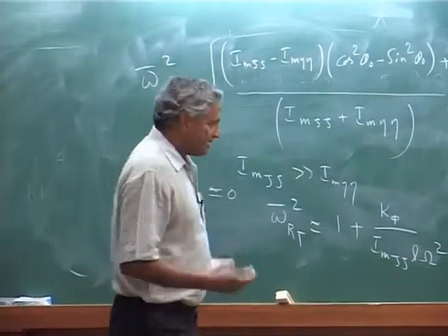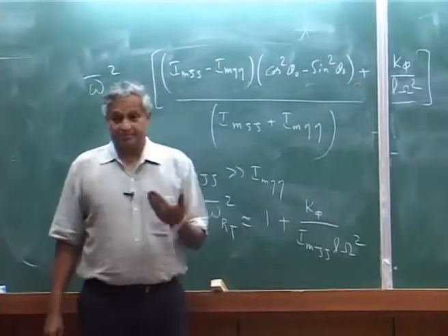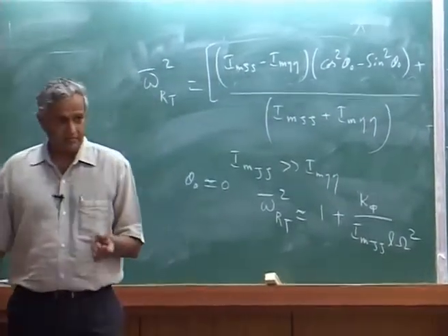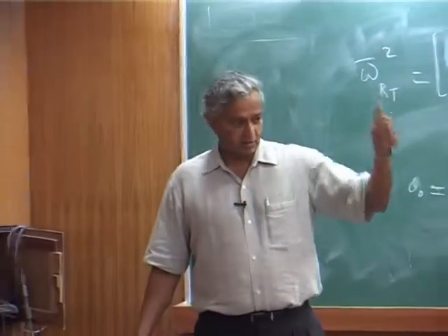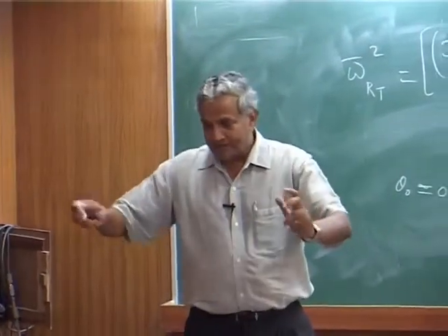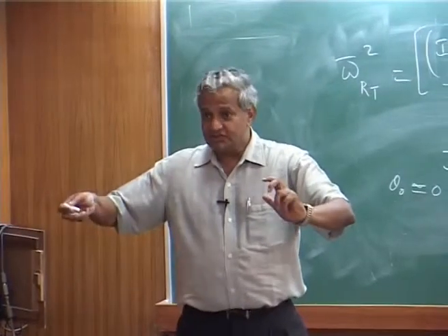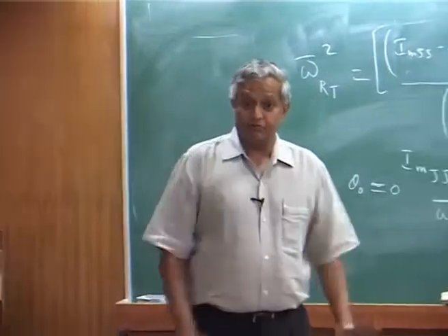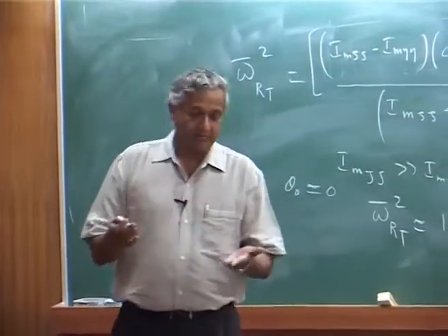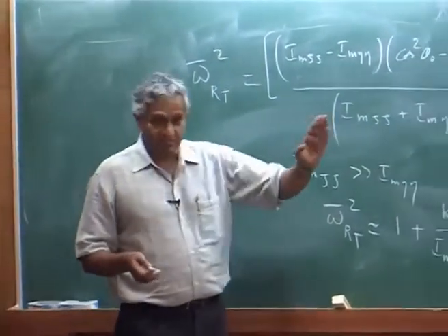So usually you try to design the control rod stiffness to be stiff. But if you take an actual blade, you have a control rod stiffness, you have the elastic GJ, the twistiness of the blade, and both will contribute to that. Those equations you have to write for the elastic blade. Here we assume the rigid blade.